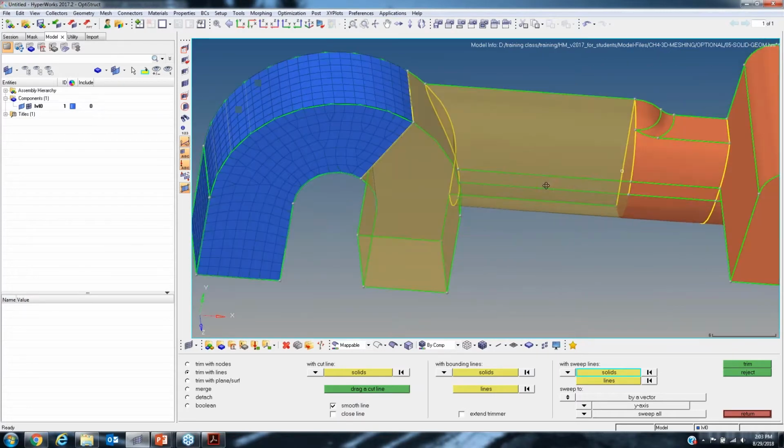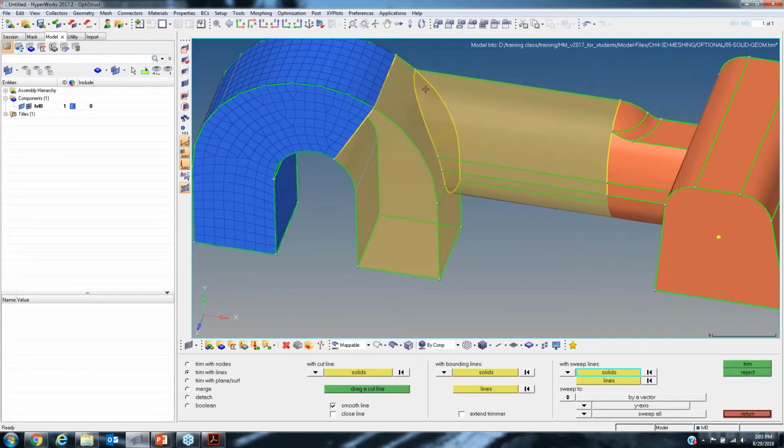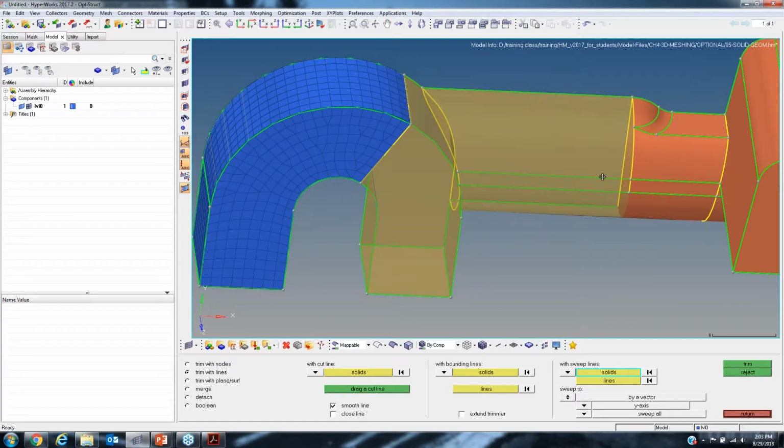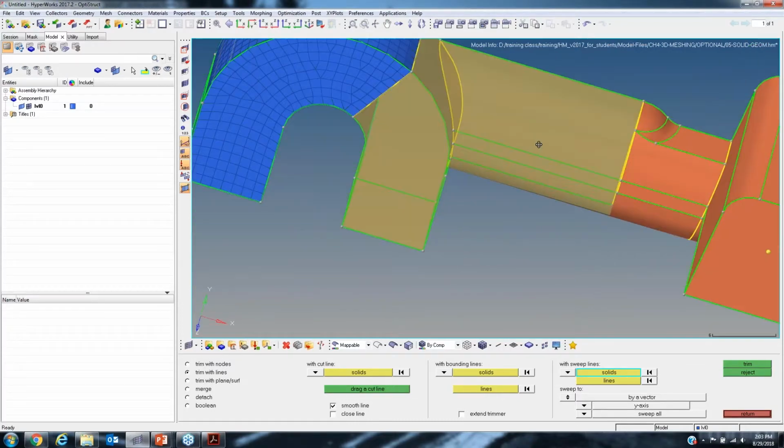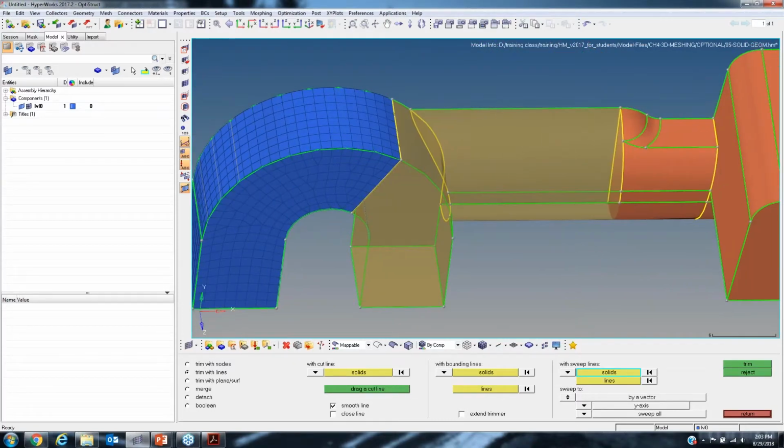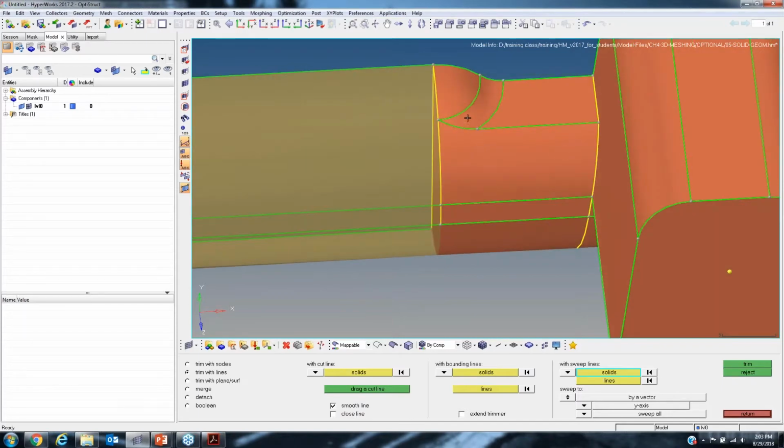right? And now that it's clear, it's mappable, which means that you can select this as your source, this as your destination, and there's no perpendicular lines, right? So everything is fine. Although over here, we have some issues because we have these perpendicular lines. So this is not mappable. Even though this one is curved, it's moving along in the direction of the map. But these are not, so we can just suppress these two here.